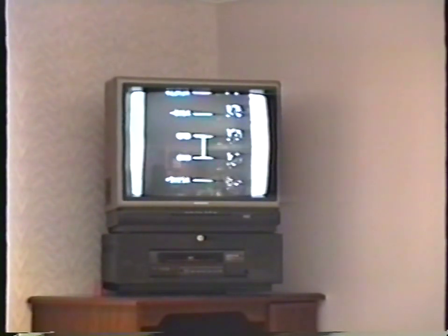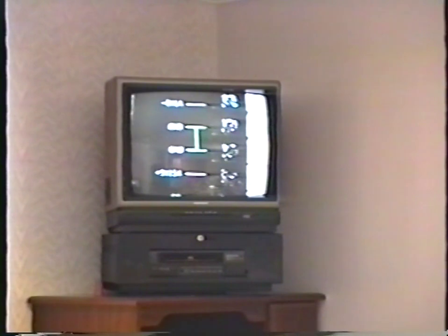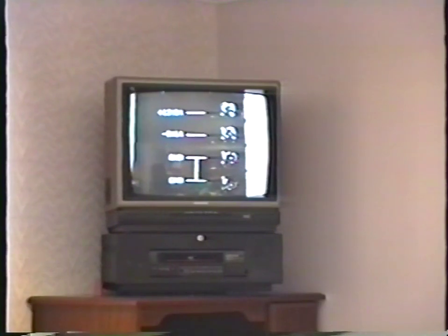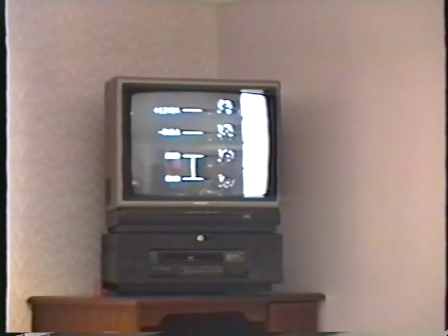The next pin up, labeled plus 5 volts at 15 amps. This one happens to be a 15 amp power supply. And then there's 2 ground connections there. There's another output that's minus 5 and another one that's plus 12. The minus 5 and plus 12 are primarily used for the audio circuits. For instance, the plus 12 usually only powers the audio amplifier. That's all it does. It just powers the audio amp. And the minus 5 is usually also for the sound generating circuits.